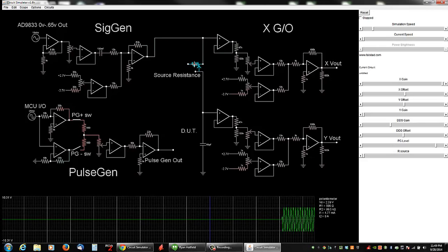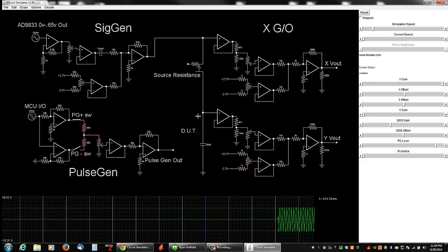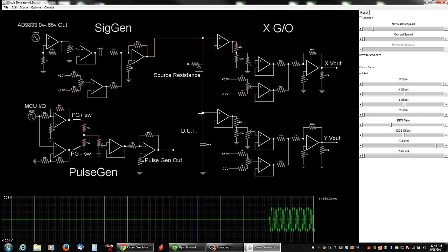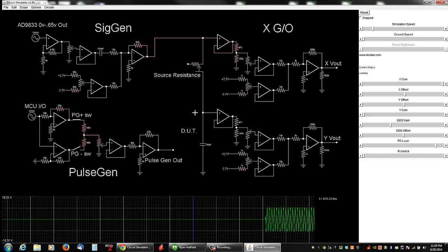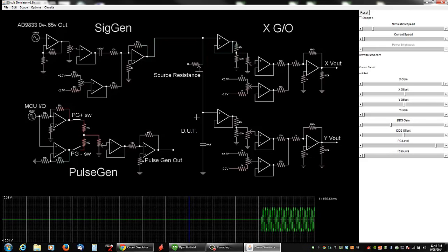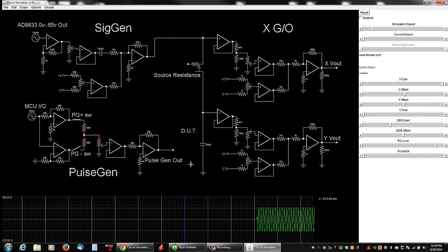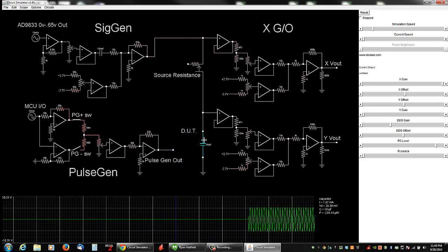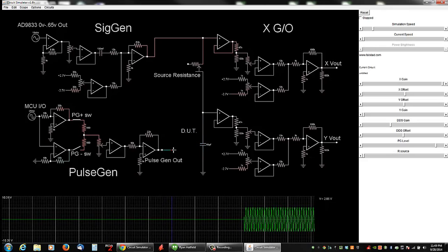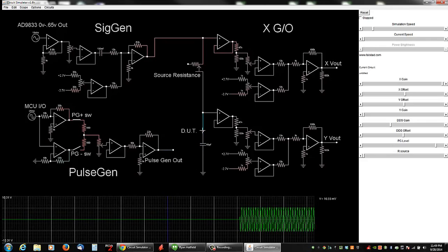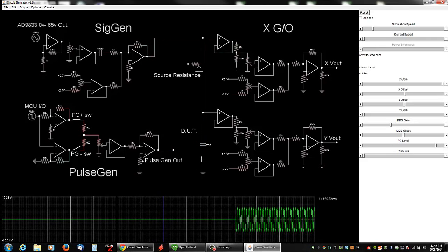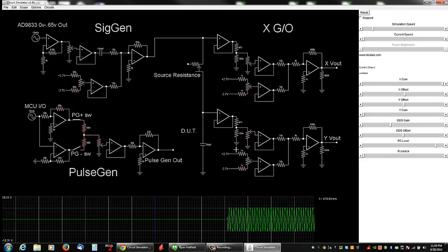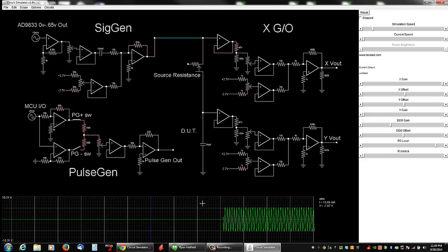And same thing in the device under test. It's just going to be basically a fan out. A couple of digital switches selecting the upper side to the test points, the signal going into the test points, and applying a ground to all those test points. And as well, the pulse generator going to any one of those test points. Maybe you got a transistor in here, you apply the pulse generator to the base, and you put the emitter up there and the collector down here, and pulse the base on and off, and you watch your signal go from a short to a open or what have you.